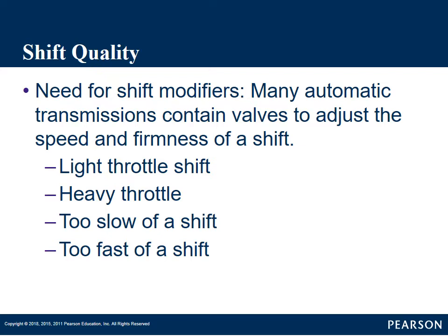But we had to make sure that we still had plenty of fluid pressure to apply and hold that clutch tight so we didn't burn the transmission up. So these shift modifiers come in play in several different places.